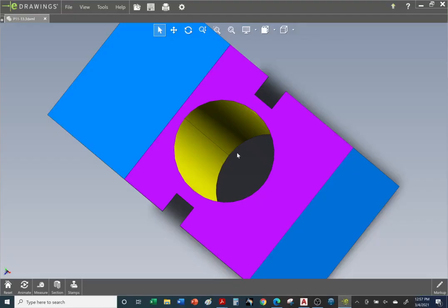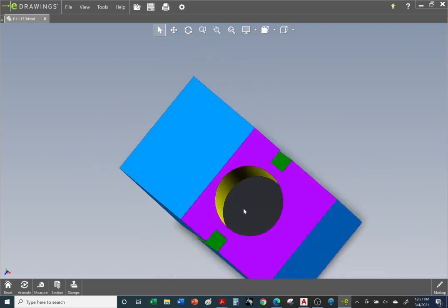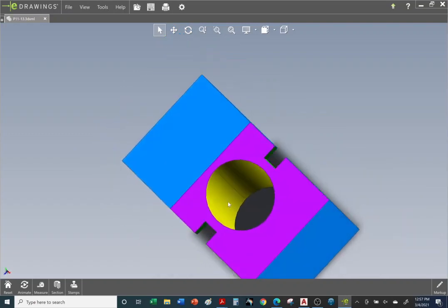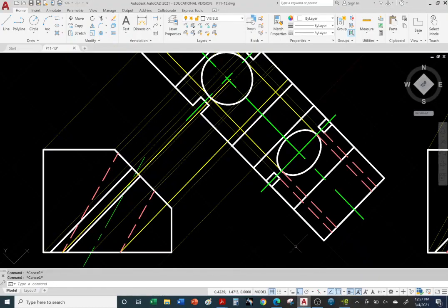Okay, so if we go back to the 3D model, we're going to model the bottom, right? Where the hole exits. And it's going to look elliptical. And we can only see part of it, so this portion will be a visible white ellipse. And the rest of it will be a red hidden ellipse. Okay, so that's the toughest part of this drawing. Okay, so let's go back.